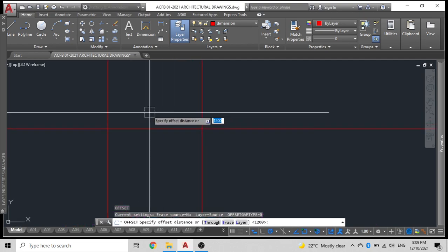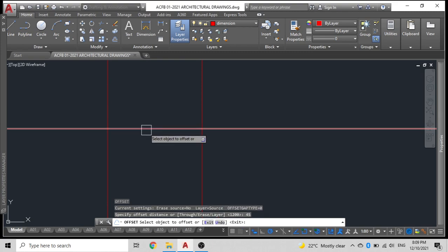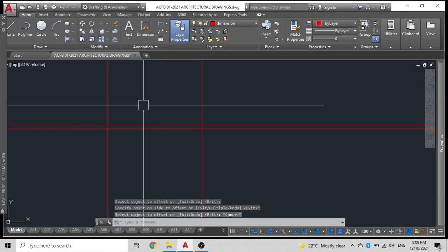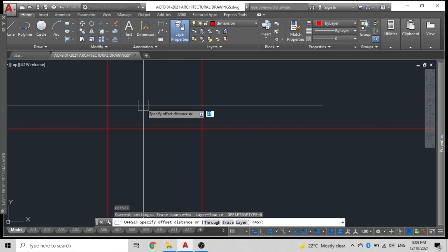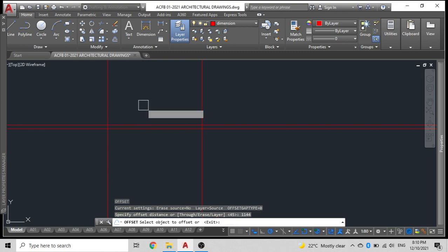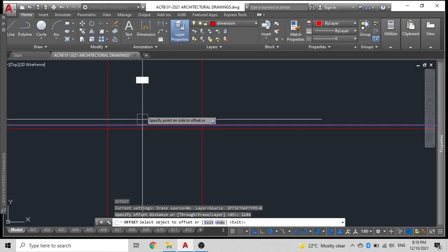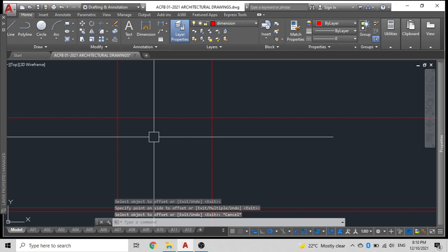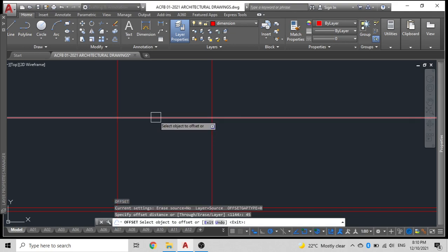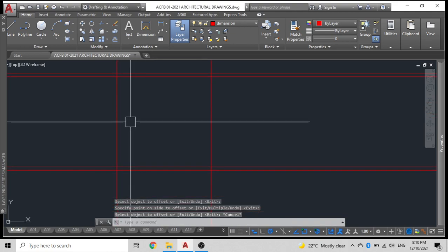Then over here, I'll add the thickness of my frame, that's 45 mm. Remember I said aluminum. Then I'll add the louvre height, that is 1144. That's 1 meter 144. Then I'll do an offset of 45 mm again. That's for the frame outer. And then I'll start to make all my drawings.